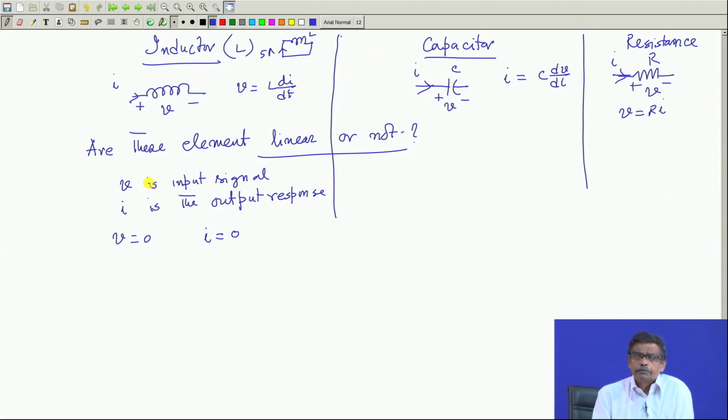Yes, very much it is possible. Most probably you have charged the inductor from some source and kept it shorted. This we explained earlier. Even so, what is the voltage applied between these 2 points of the inductor? 0, but still there is current.